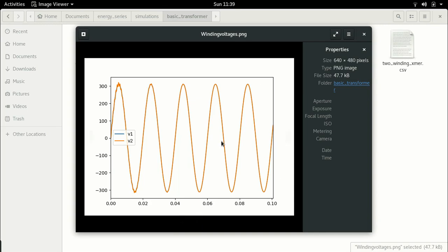So with this, we can conclude that the reason for instability was that the system was very sensitive. And this is one of the things that you need to understand about any simulation: there are two ways to simulate a system that is sensitive. If you determine that your system is sensitive and you must simulate a sensitive system, then you have to decrease the integration time step. However, if there is a possibility of making your system less sensitive by changing some resistances, then we should examine that as well, right? So we now have a stable simulation, which means that we now have a working transformer model.